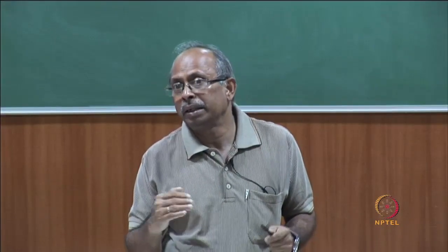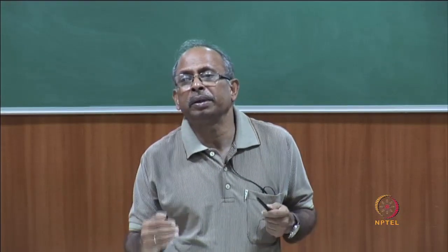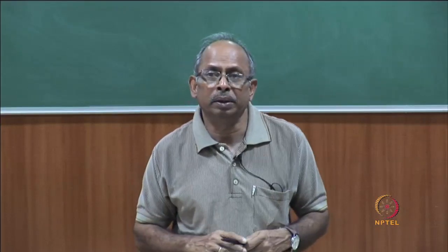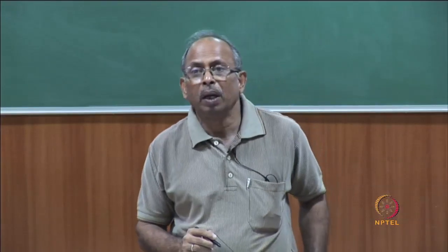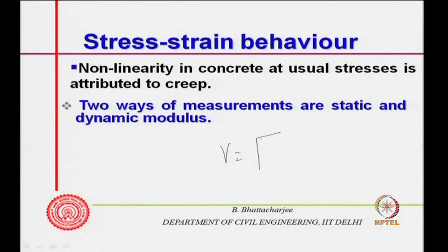So, we measure strain at corresponding stress steps, and from the stress strain curve we can find the modulus of elasticity. But from concepts of mechanical waves traveling in solid media, we know the velocity in the media is a function of E, root E over rho actually. So, velocity is proportional to root of E over rho.